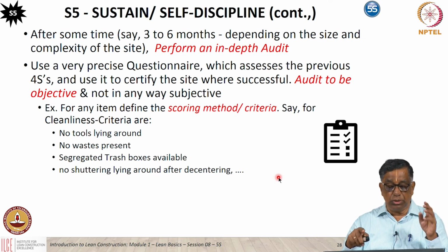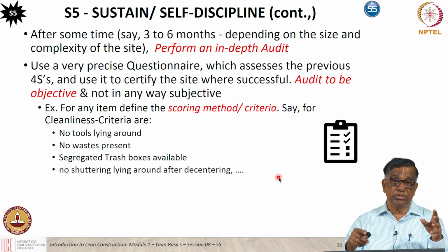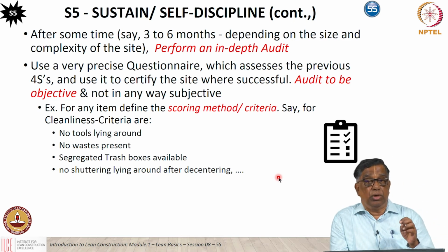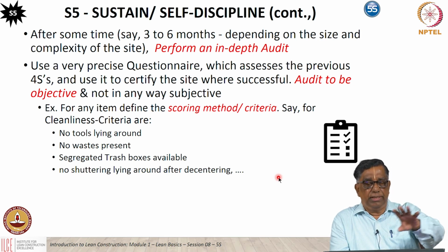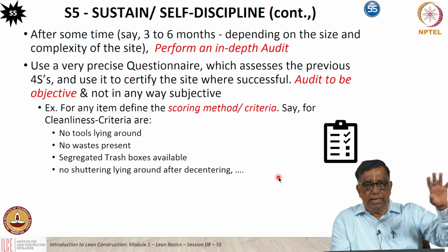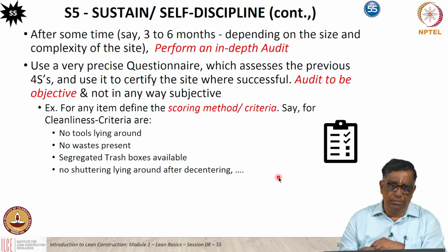For example, sort, the cleanliness criteria. Do you have tools lying around, any waste on the ground, or is trash segregated and taken out as quickly as possible? And shuttering material, something I have seen, should never be allowed to lie on the ground once you have removed it from the structure. It immediately has to go to the yard, get properly cleaned up, and then return back to the site.